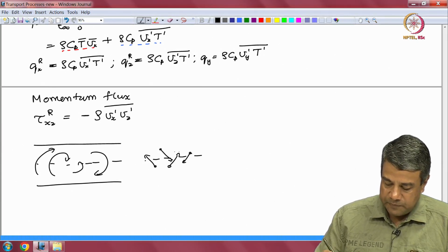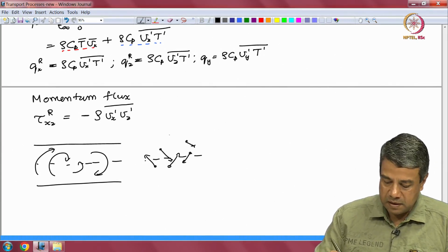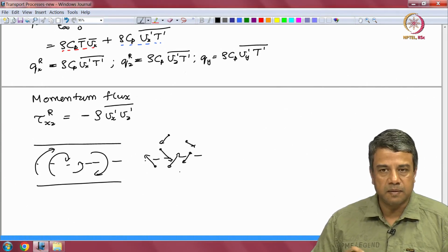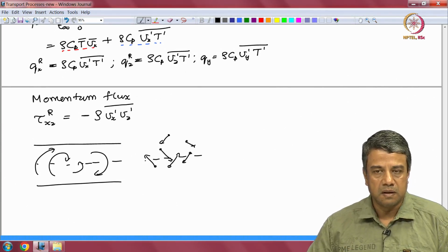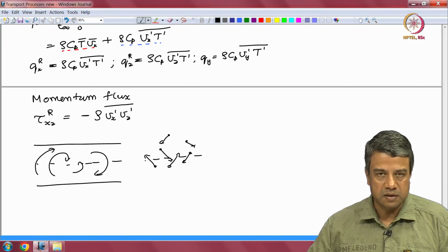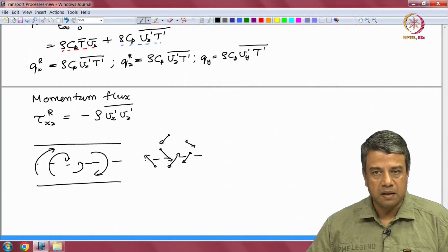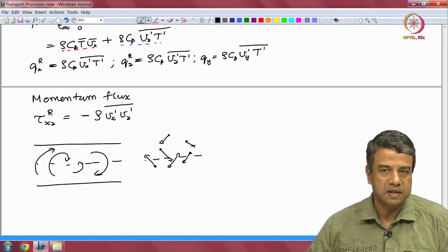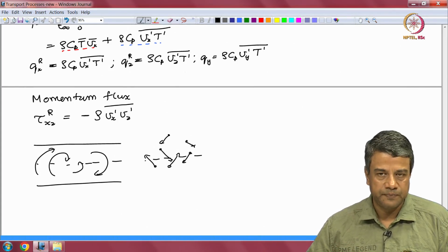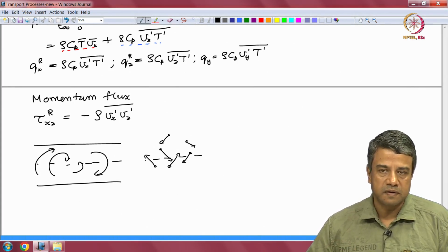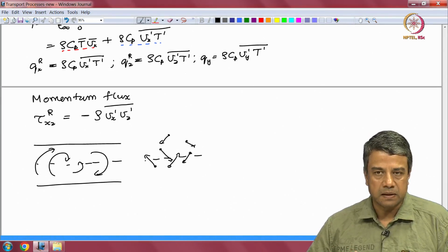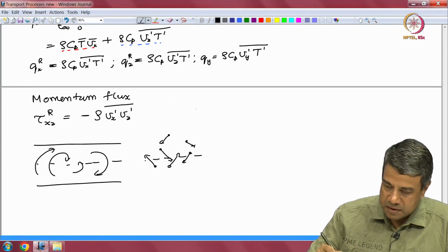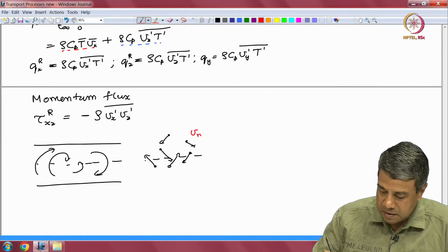In a gas, it will be discrete transport of molecules. In a liquid, it will be due to cooperative motion and so on. But basically, we are looking at the number of molecules crossing per unit time across a surface upward as opposed to downward. And if there is a concentration difference, then we use that in order to find out the net flux across a surface based upon the root mean square fluctuating velocity V RMS.